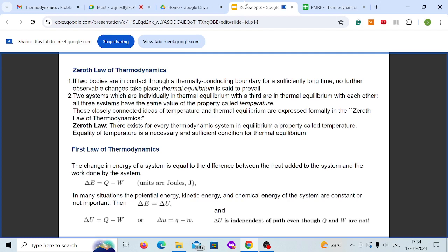And then the first law stated that if I want to go between two states, and not a cyclic process, then the net difference between the heat and work transfer goes into raising the energy of the system. So you are supplying some Q, you are taking away some energy as work, but Q and W are both energies. So this difference in energy should be going somewhere. It goes inside the system, raising its own energy. That is defined as the internal energy.